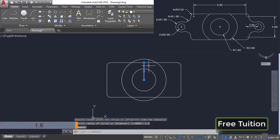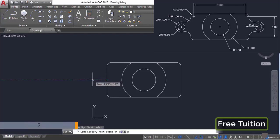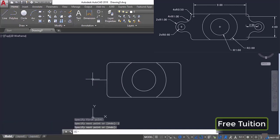Now we don't need this line. Also we don't need this portion, so I'll trim it. So select trim, press enter, click on this part and click on this part. So this portion is complete. Now let's move on to the next portion. Here we need to add another line with a length of 2 units. So I'll click on this midpoint and I'll enter a length of 2 units and press enter. Press enter again to exit this command.